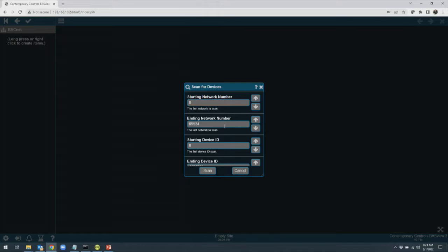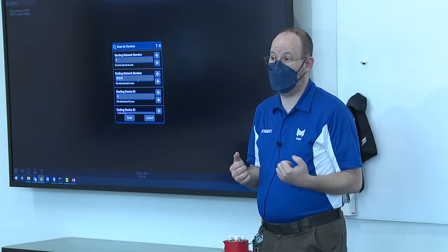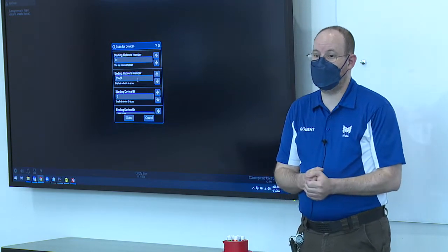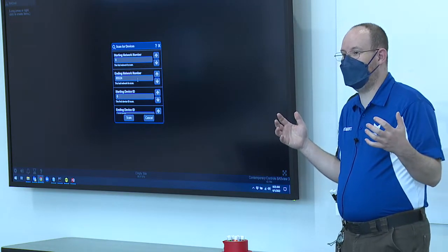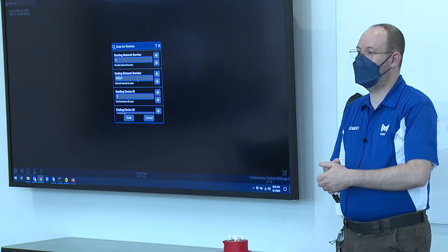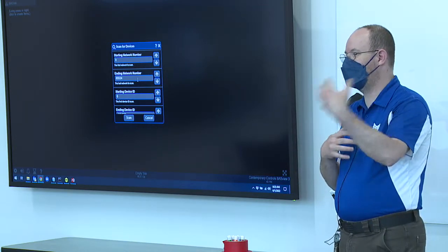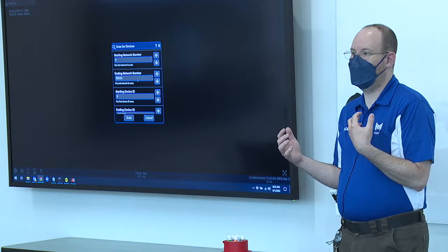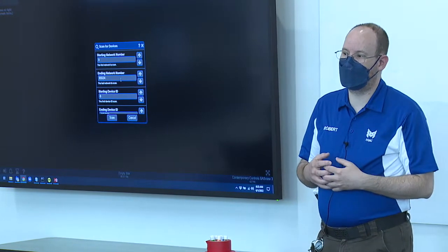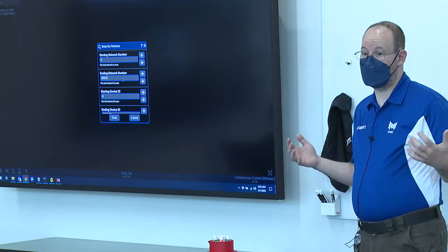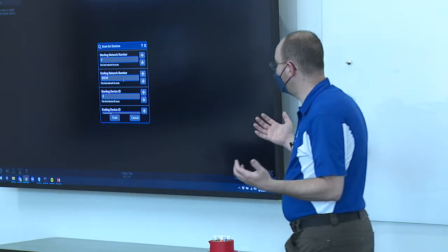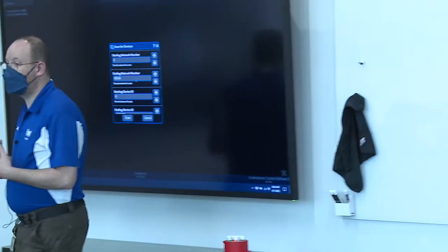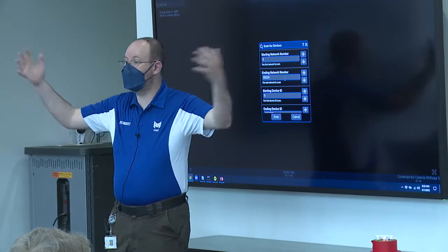One of the things you never want to actually have happen with BACnet is you never want to do a scan like this and get results really fast. Counterintuitively, that's a really bad thing. If you get results fast, that means the scan didn't actually succeed properly. So if you're not sitting and twiddling your thumbs for 30 seconds to several minutes, something went wrong. And part of the reason for that is when BACnet is doing its Who-Is statement,